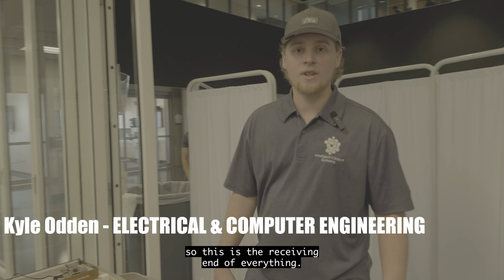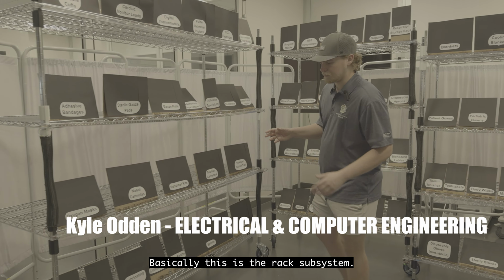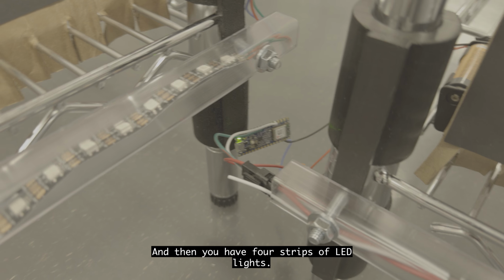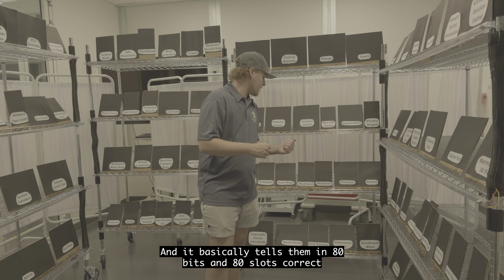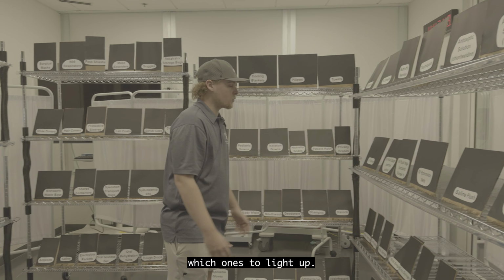All right, so this is the receiving end of everything. Basically, this is the rack subsystem. Each one is comprised of an Arduino in the bottom left, so 4 Arduinos total, and then you have 4 strips of LED lights. Now, the Raspberry Pi communicates to the Arduinos, and it basically tells them in 80 bits, in 80 slots per rack, which ones to light up.